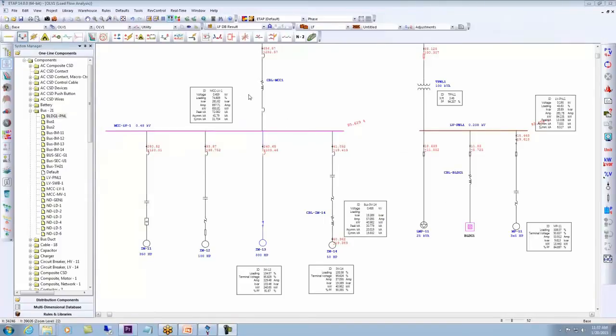Now in this case we are showing LoadFlow and short circuit, but also in the first release you'll be able to do arc flash results as well. So we'll have LoadFlow, short circuit, arc flash results. Instead of building new ones, I just wanted to mention that so everyone knows you will be able to apply arc flash conditions in ETAP 14 as well.